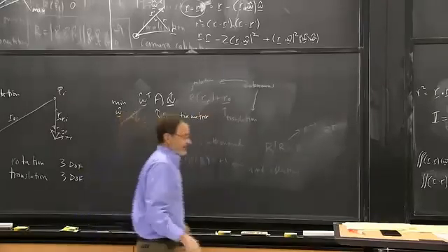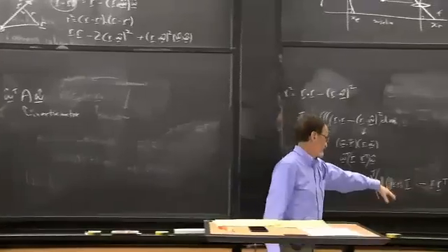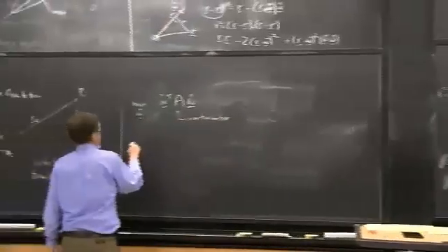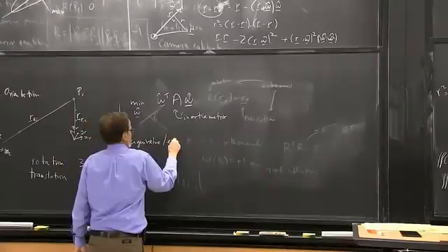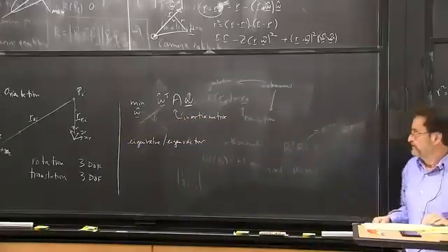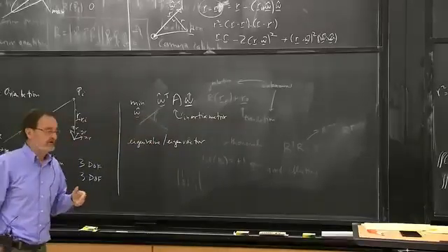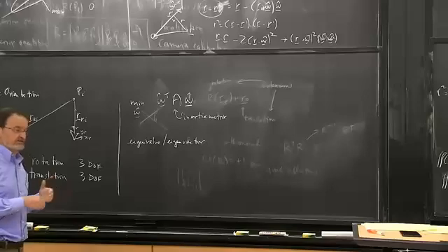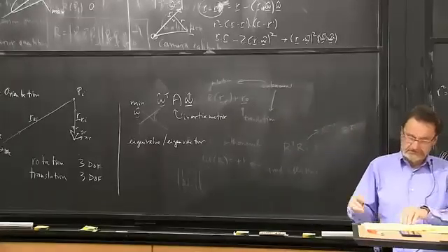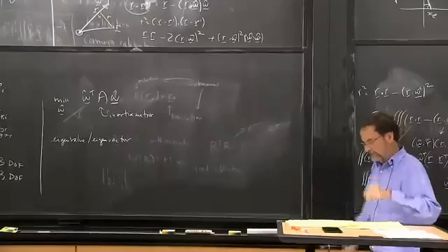And even though it says A, this is called the inertia matrix. So given some three-dimensional shape, I can compute this 3x3 inertia matrix. Or given a cloud of points in 3D, I can compute this matrix. And this is just the detail of how to do it from the points. So what is that problem? Well, that's just the classic eigenvalue eigenvector problem. The axis I want for the minimization is the eigenvector associated with the smallest eigenvalue, obviously. And then I can look for the other axis that maximizes it, and that's the eigenvector corresponding to the largest eigenvalue. And then there's a third one, which is in between. Those three axes are at right angles to each other. Or in some nasty cases they're not, but we can make them at right angles to each other. So it's a very simple eigenvalue eigenvector problem.